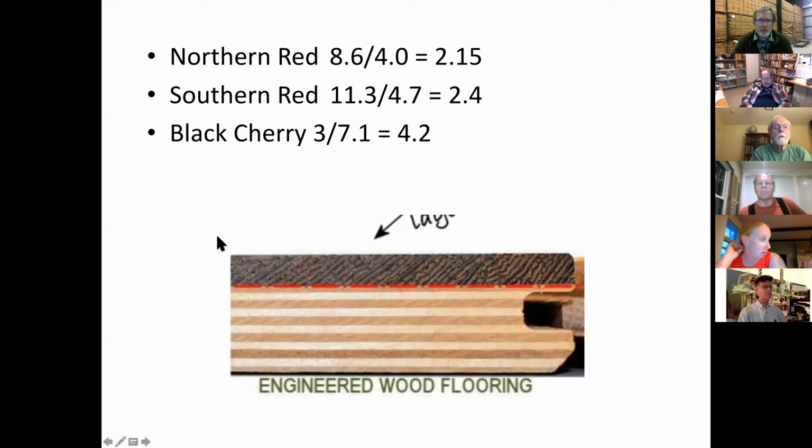I also worry in this particular example, this is engineered wood flooring where you have plywood and a face veneer on top of that, which would be gluing veneer. You have to be very careful in these situations because if the glue bond is good, it won't fail. I still don't worry about the structural integrity of the glue bond. But this thin wear layer can have enough influence as it shrinks that it can actually override the plywood underneath and cause that piece to cup. So having large differences in face gluing like this, yes, makes a big difference.